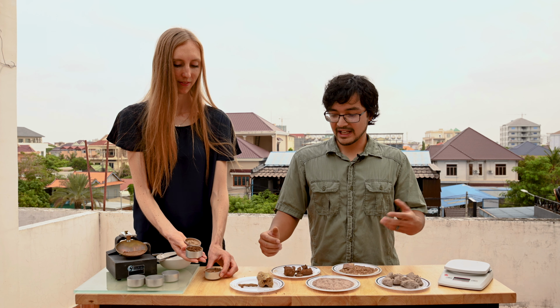One of the first things that you'll want to comment on when you're creating your boring log or your sample log is the soil moisture content. And this is all the same soil sample at different moisture contents. The one on this side is a dry soil sample, and dry soil samples are characterized by their dry or dusty appearance. For fine-grained soils, the dry samples might be very hard.